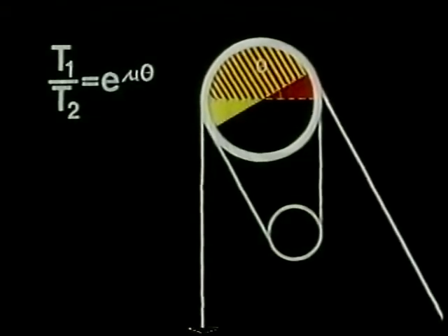This then gives an angle theta equal to the sum of the two contact angles between the rope and the sheave, thus increasing the traction. This is called a double wrap drive. Yes, we had to use a double wrap system in this case to achieve the necessary traction. We were using 8 ropes to suspend the load, and 8 ropes double wrap gave us the necessary traction.